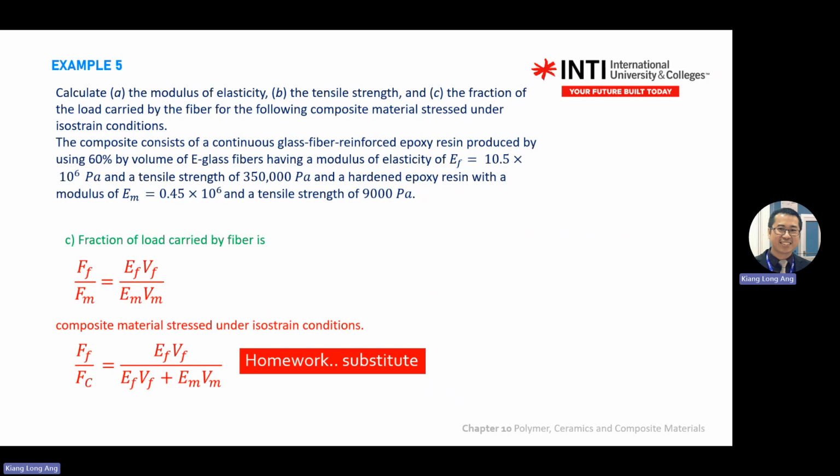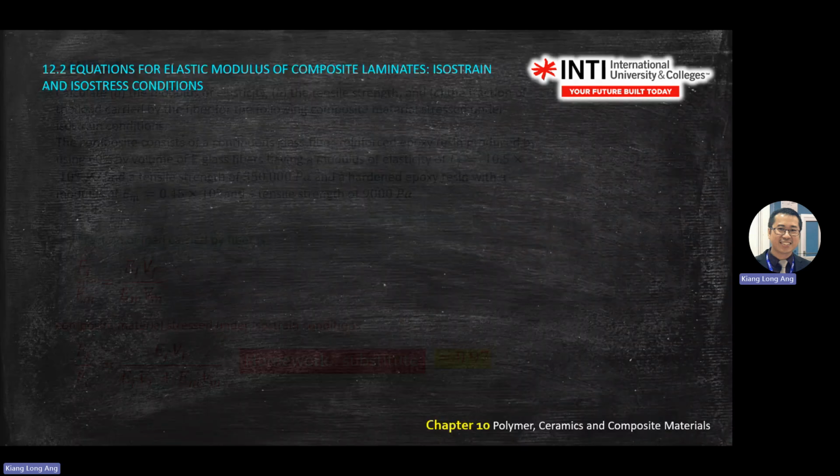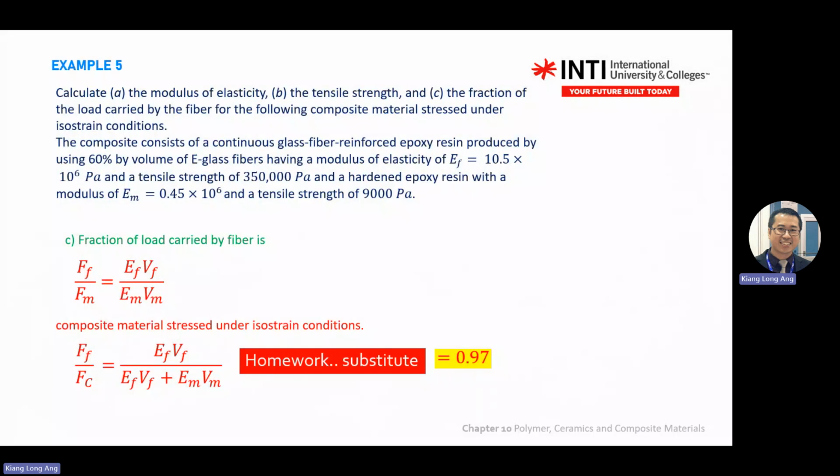If the question asks you fraction of load carried by fiber and matrix, it means this one, you use this formula. If the question, like example 5, asks you to find the fraction of load carried by fiber for the composite material, then you use F and C, not F and M. So this is the careless mistake. Okay, so the answer will be 97%.